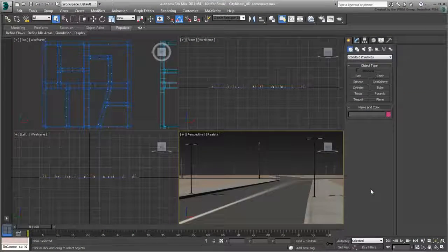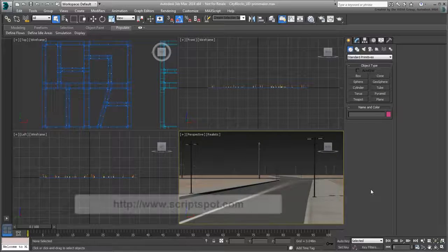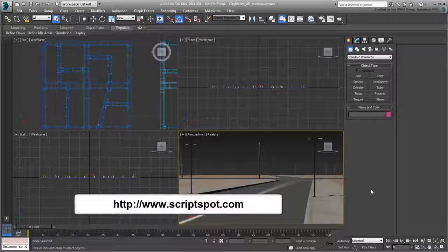So far, you duplicated and placed light poles and other street lights using duplication tools such as Array and Spacing tool. Here, use an even easier and more intuitive approach by turning editable poly objects into standard 3ds Max primitives. For that, use a free downloadable script called Primitive Maker by Garp. This extremely helpful tool can be found where most other free scripts are found, namely at scriptspot.com.